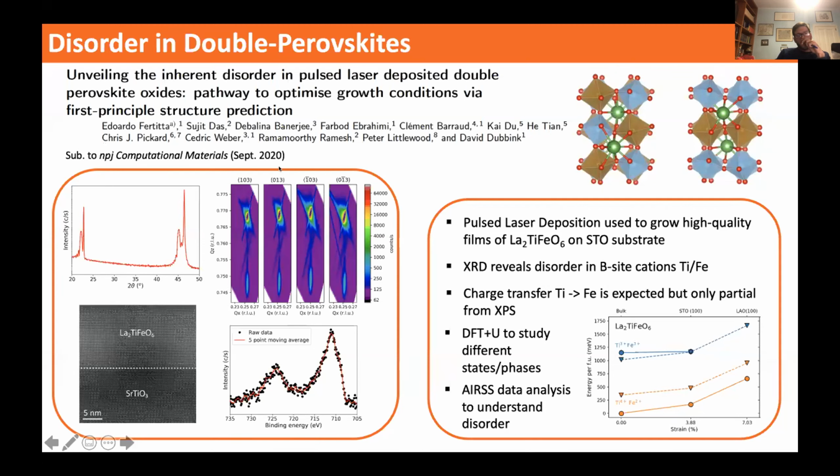Experimental results show that by using PLD, pulsed laser deposition, we were able to get very clean and very regular crystals, which, however, didn't present any B-site order, meaning the concurrence between crystal structures, for instance, being rock salt and layered or others, that were causing the absence of a clear order that otherwise we would observe in the XRD diffraction pattern.